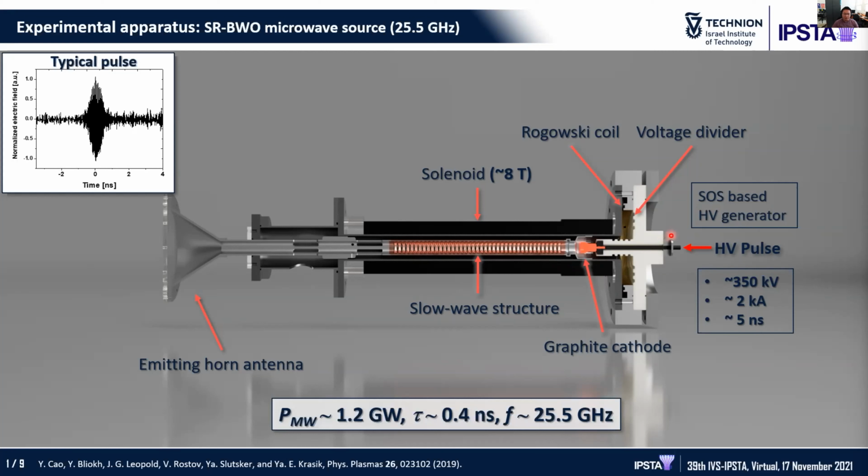First, this slow wave structure is designed specifically for this voltage, in order to produce this frequency. And second, if you want to change it, first you need to change the curvature, of course, and also the velocity of the electrons should be synchronized, or designed specifically, confirmed by simulation to see what the frequency output is. Okay, thank you very much.